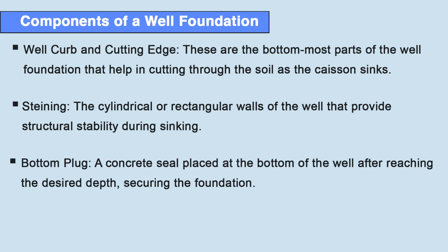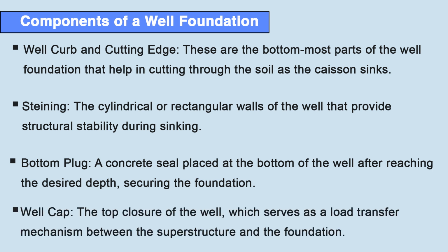Third is bottom plug, a concrete seal placed at the bottom of the well after reaching the desired depth, securing the foundation. Fourth is well cap, the top closure of the well which serves as the load transfer mechanism between the superstructure and the foundation.